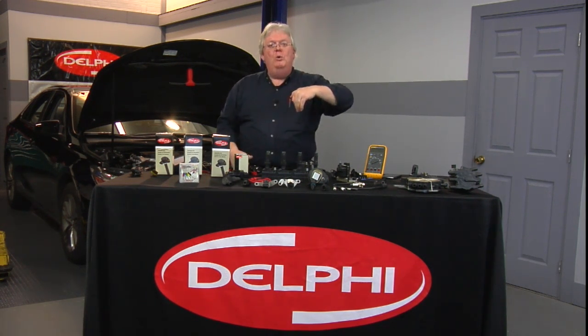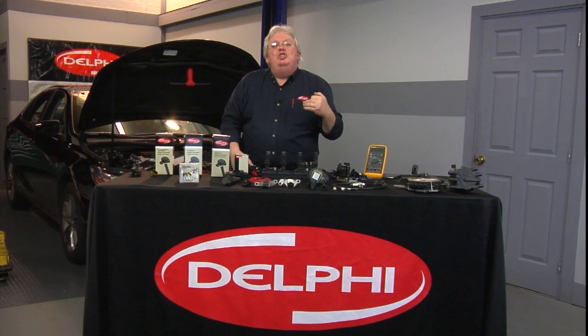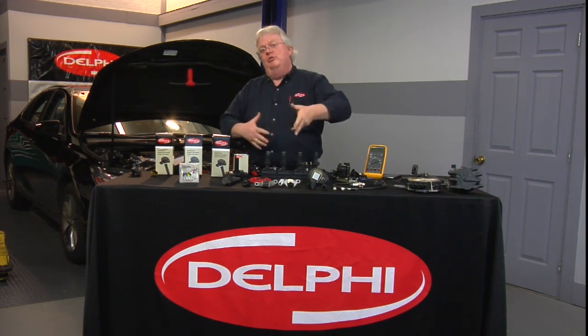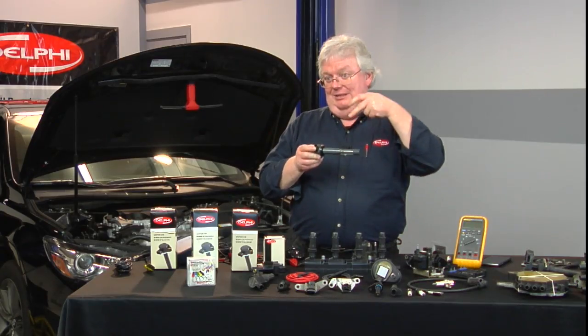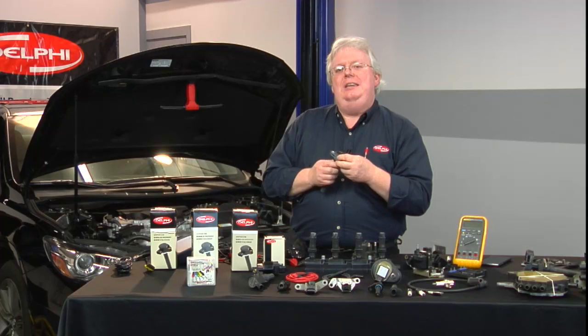We'll have a very low firing line because it didn't take much to jump that gap as it did to go through the cylinder. So you're looking for a breakdown of spark under the loaded conditions. Otherwise, there's no looking at it because it's internal and there's no real testing.